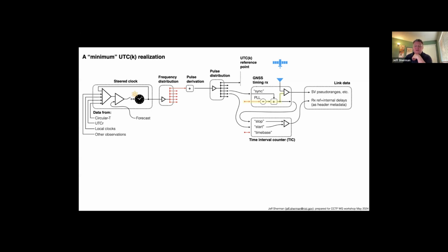So it's important, especially, to keep that path constant once calibrated, and attach this additional time interval counter I show on the bottom to measure the delay through the timing receiver. And I'm sure the link talk will expound upon this, but I point it out because it's an exception to the rule of the pulse really being the best place to consider as a reference.